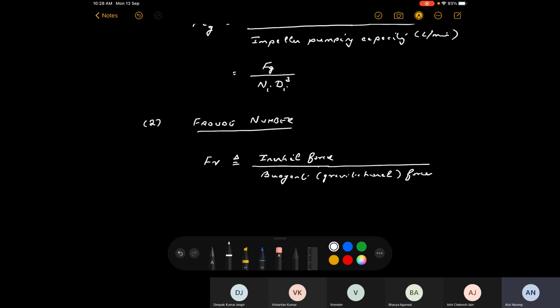Now, how do you calculate it? This is a good thing to remember. Whenever you have an inertial force, it is due to inertial stresses. Now, the inertial stress always has order of magnitude of rho multiplied by the velocity squared. So, in this case, the most obvious velocity to use is again the impeller tip. This is a measure of the stress created by convective momentum transport, and that must be multiplied by area to get force. So it is multiplied by di squared.